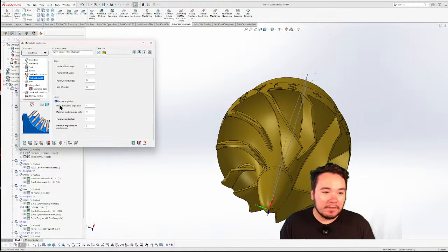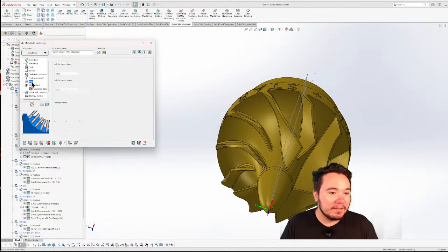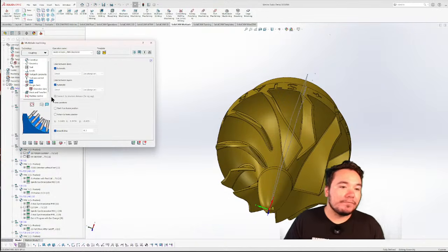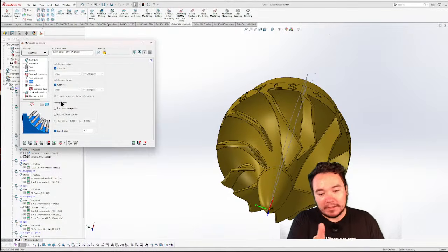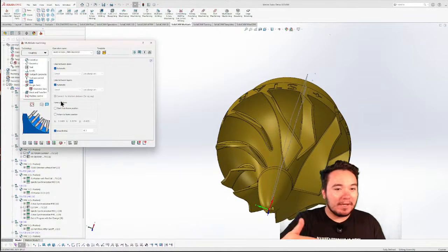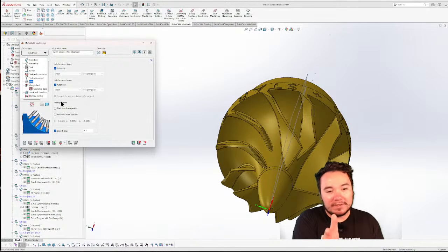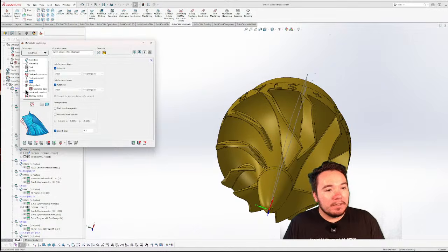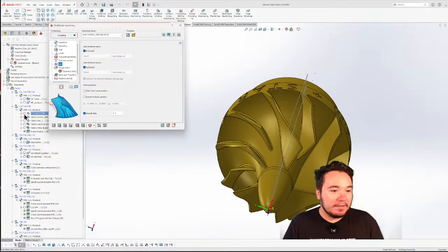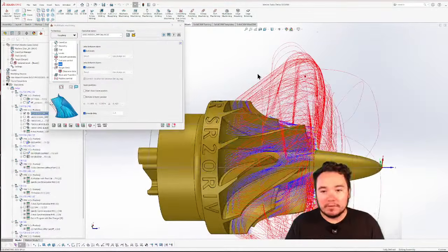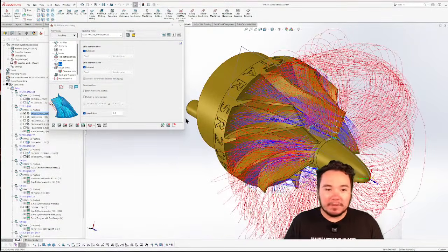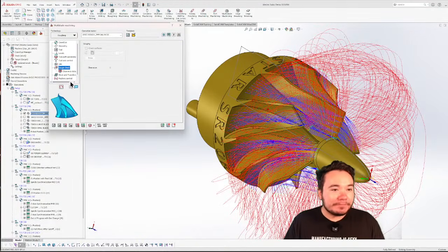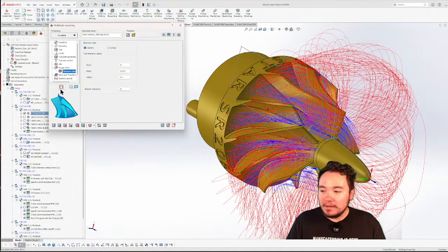We gave it a slight machining angle limit, just telling it not to go past 90, and at 90 axially. So it's stationed like at a 0 or negative 90, and we said I don't want it to go past, you know, 90 degrees or 0 axially. And then link, I let it go automatic. I did turn smooth link on, which is why you see that nice little curvature retract there. I thought it looked nice. It looks good on the machine. No check surfaces. It did pretty well off of that.